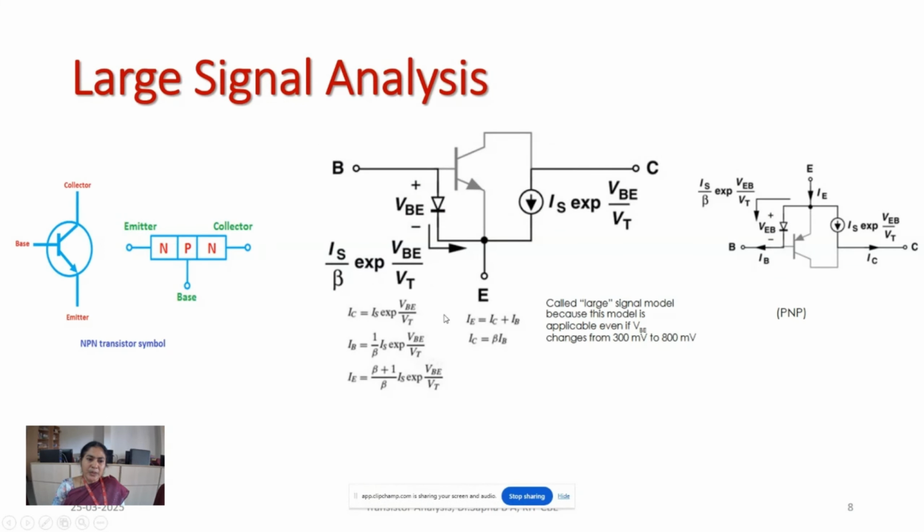We also know that the transistor, when it is mainly analyzed during forward bias, has the input junction always forward biased, that is between the emitter and base, and the collector to base terminal always reverse biased. So if you consider a common emitter transistor, which is basically used in amplifier circuits, we have forward biasing at the input, between the base and the emitter terminal, where the emitter is grounded and the base is acting as the input terminal.